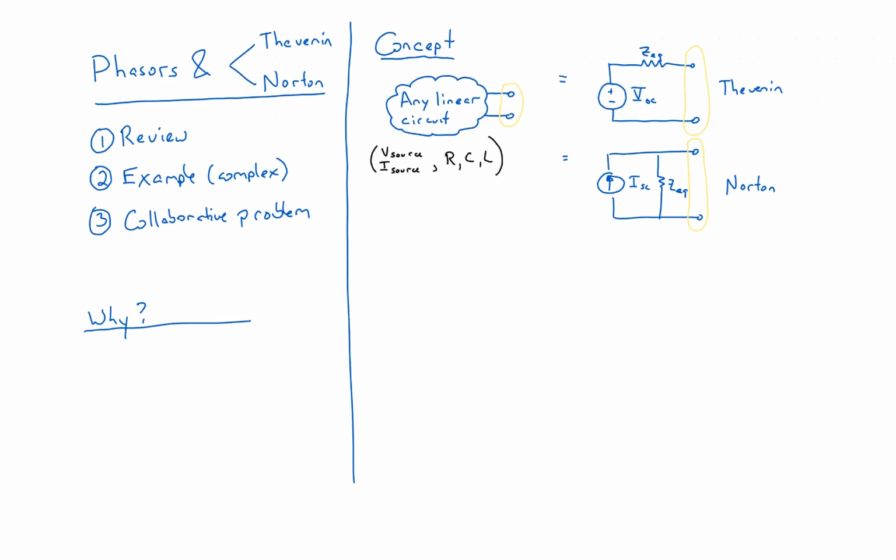As an example, let's say you want a battery that powers a project, and you design your battery to be a 3-volt battery, and you go power your motor with this 3-volt battery. The specification of the motor is that when you give it 3 volts, it turns at 100 RPM, and when you hook it up, it doesn't work. And it should, because it's a 3-volt battery and a 3-volt motor. The reason it doesn't work is that you didn't find the Thevenin equivalent of either component.